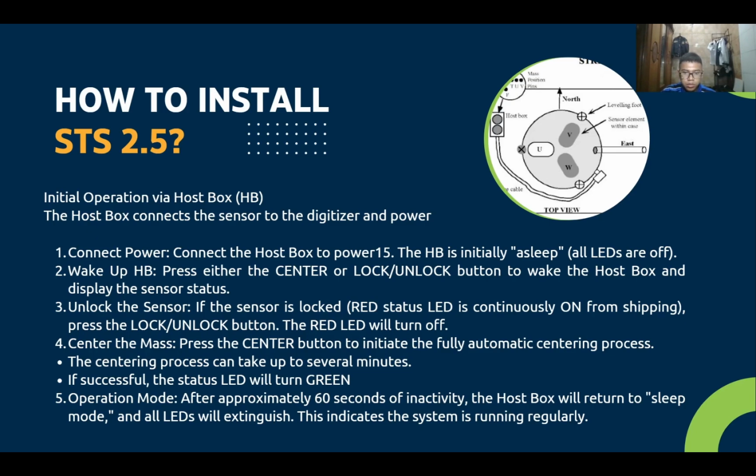Press the center button to initiate the fully automatic centering process. The centering process can take up to several minutes, and if successful, the status light will turn green. After approximately 60 seconds of inactivity, the hostbox will return to sleep mode and all lights will extinguish. This indicates the system is running regularly.